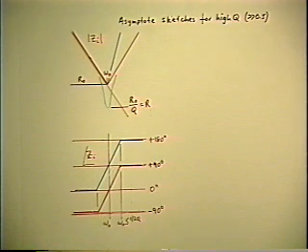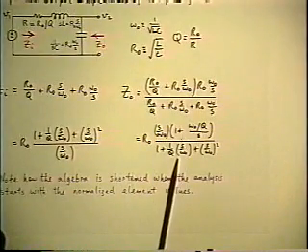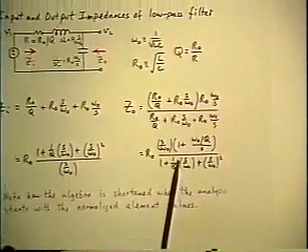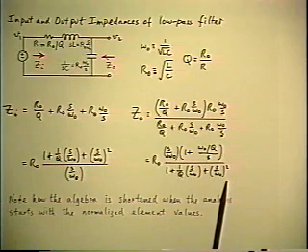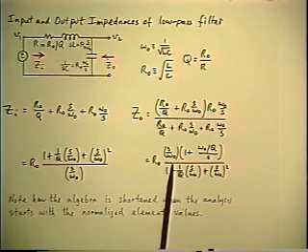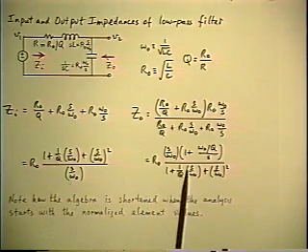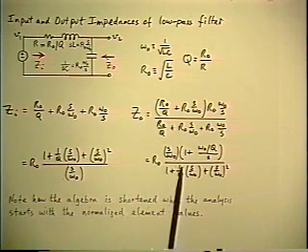So there's an example of a graphical construction in which you build up more complicated functions by using the simpler building blocks. Now you can do the same thing with the output impedance. Here's the output impedance function. It's a little more complicated. This time the quadratic is back in the denominator, but there's an S term in the numerator, so the combination of the two of them can be identified as the reciprocal of the input impedance function that we just derived. We can keep those two terms together already, since we've already constructed that.